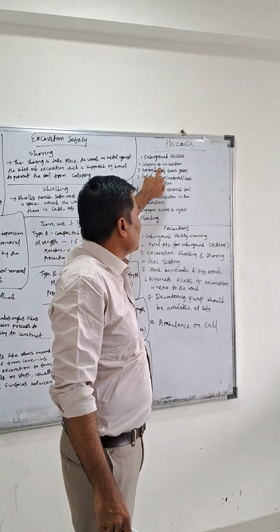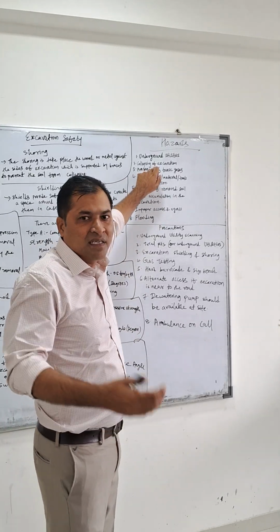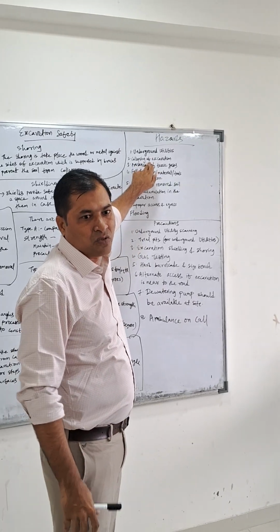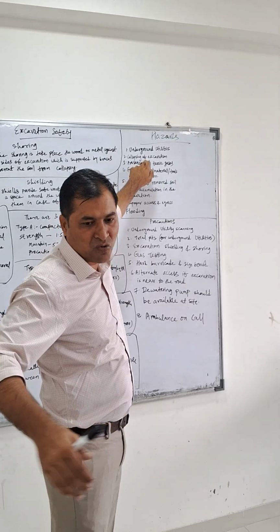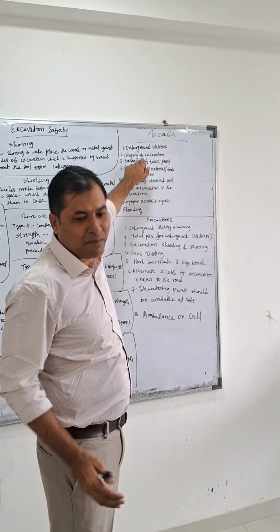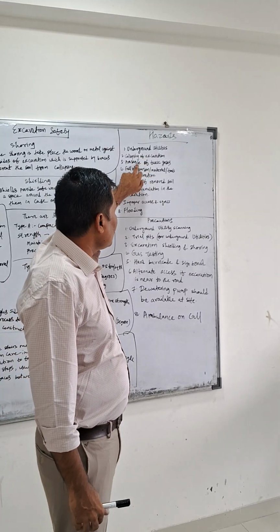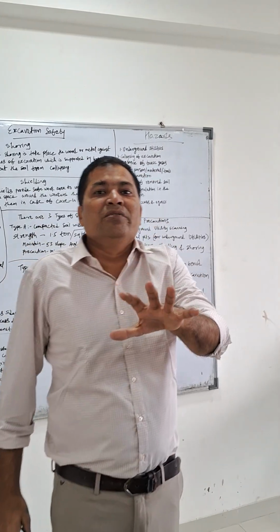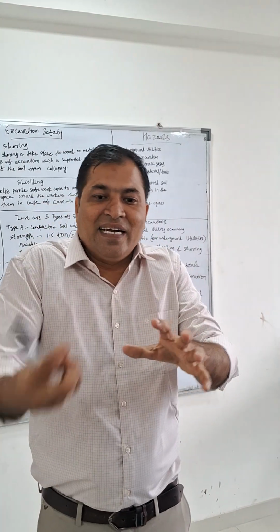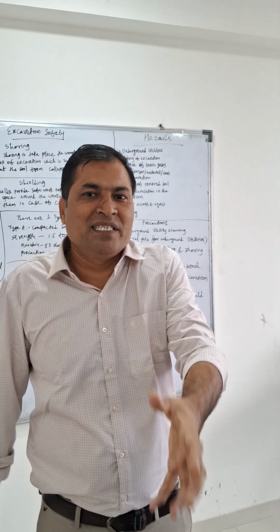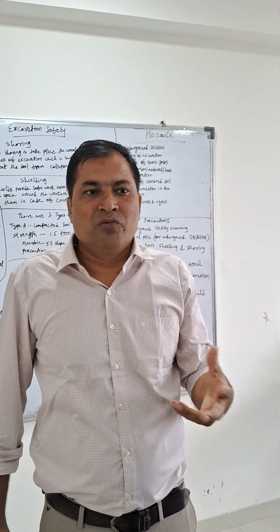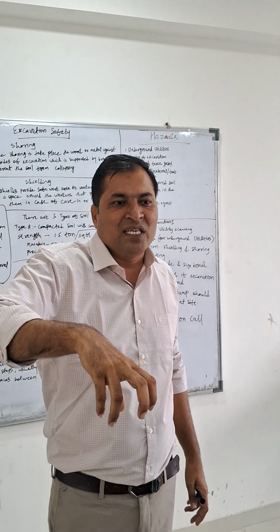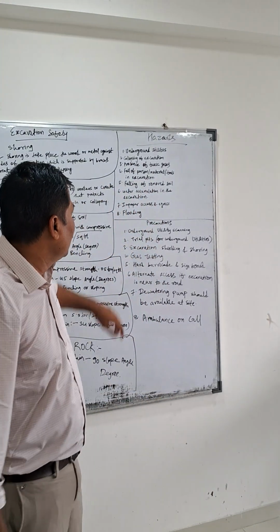Collapsing of excavation: yes, once you start excavating, there is the possibility that the whole mud may go down and collapse. The soil which you are putting at the sides may also collapse into the same area. Presence of toxic gases: if you are excavating, there may be the possibility that some kind of toxic gases are present and will come out. So again you have to put detectors over there, check the level of the toxic gases, and then work over there.